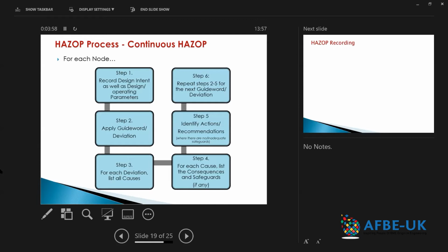So do you, for example, need an additional temperature trip of dissimilar design, so you avoid common cause failures, so that both temperature transmitters are not affected by that same scenario? Those are the sorts of discussions you look at. And then you determine, right, we need an additional dissimilar temperature trip as an example. So that goes in as a recommendation.